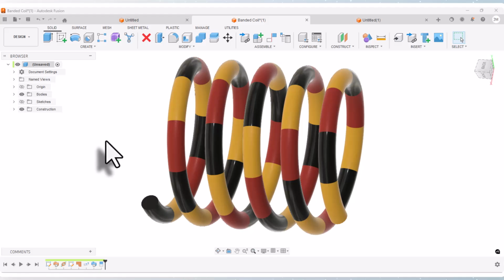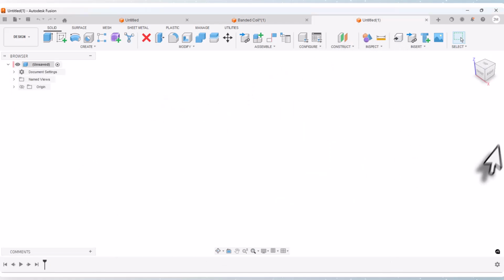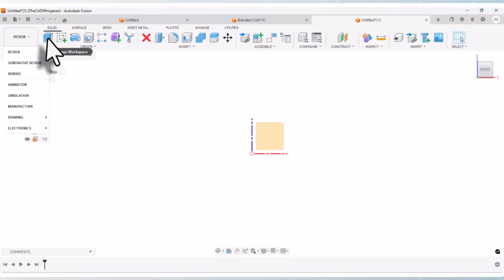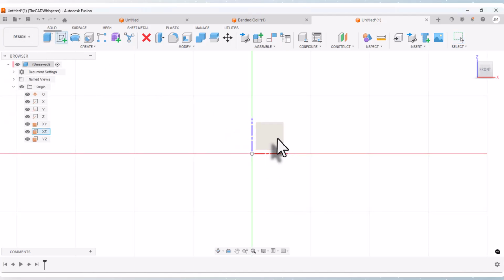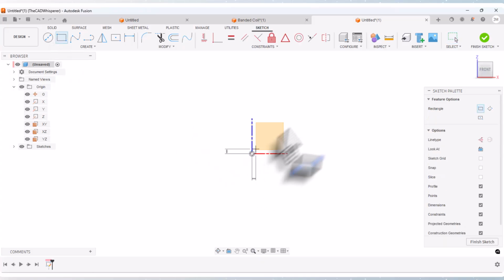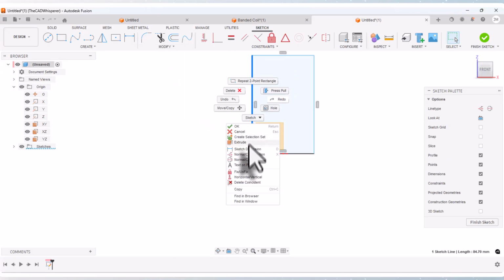Let's take a look at how to set something like this up, and then we'll look at the implications of being able to model this geometry. So I'm going to start a new sketch, and I'll do it on the front plane. And so let's turn on that visibility, and I'll do a sketch. And I'm going to draw a polygon at the origin, and let's make this a diameter, let's say, of 100.